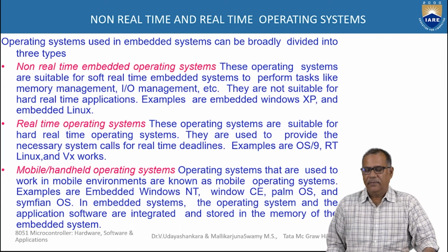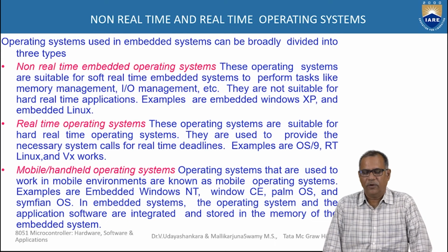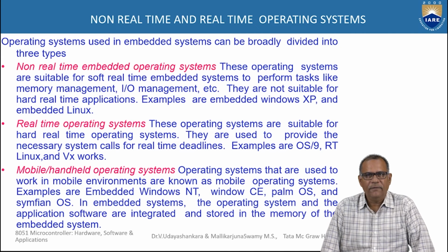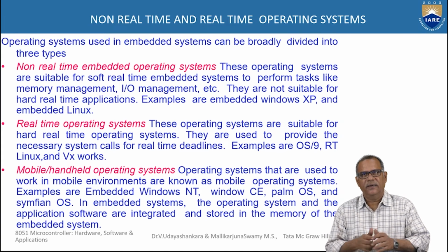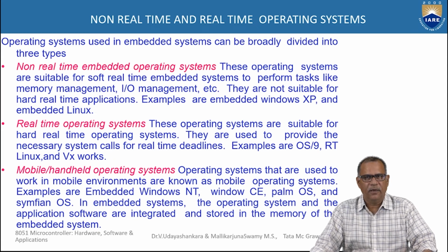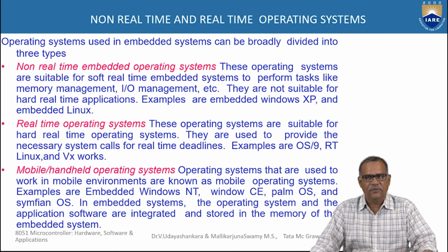Now, non-real-time and real-time operating systems. What is a non-real-time embedded operating system? These are suitable for soft real-time embedded systems to perform tasks like memory management, I/O management, etc. And they are not suitable for hard real-time applications. Examples are embedded Windows XP and embedded Linux.